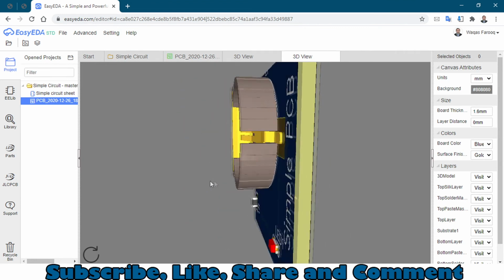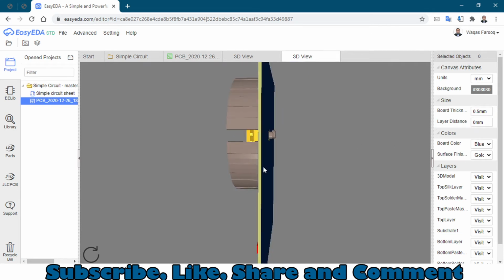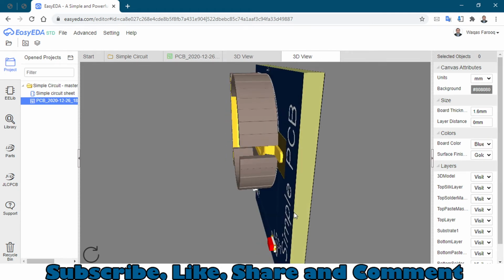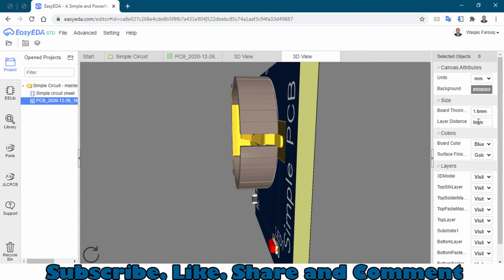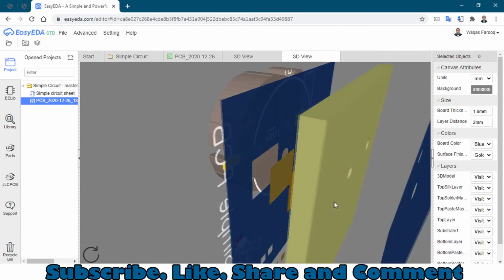Or if you want to see all the layers separately, you can change the thickness of the PCB board, like 0.5. You can change the thickness as well, but I think 1.6 mm is very appropriate. On the bottom you can see there is a layer distance, so you can change the layer distance like 2.0 and click on this canvas. As you can see, you can check every layer separately.